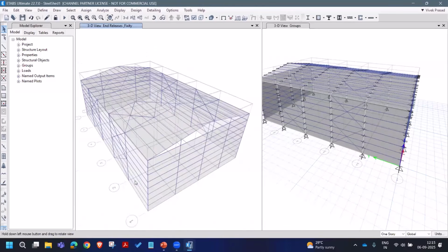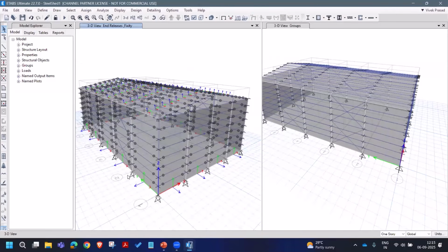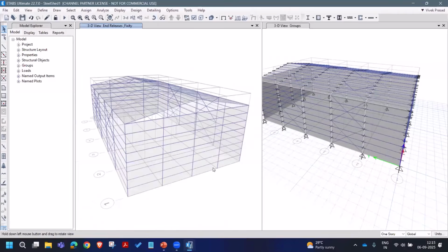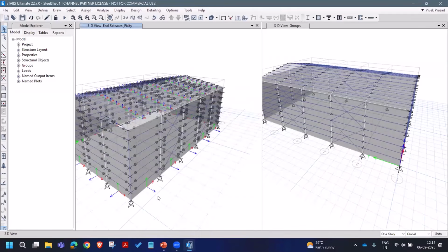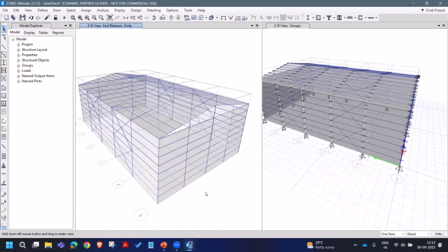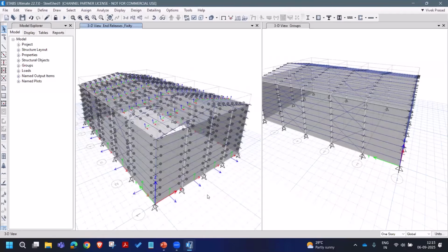You can see the local axes are auto created, using the auto option, so local axis 3 will be perpendicular, outwards of the building. It will be helpful in other cases, but for wind loading, we prefer that these are aligned in the same direction for the parallel walls.